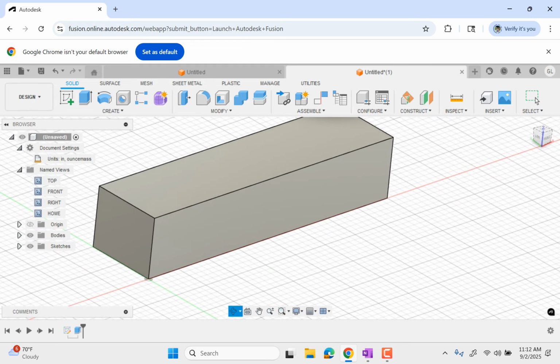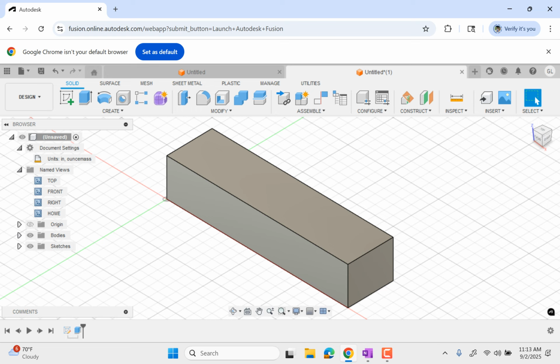If you get way out of whack, you can always close the rotation thing by going right click, cancel, and then go back to the home view, and it'll take you back to the starting position. That also happens if sometimes you'll zoom so far out you have no idea where the thing is anymore. Just click on home and you can start the view over again.